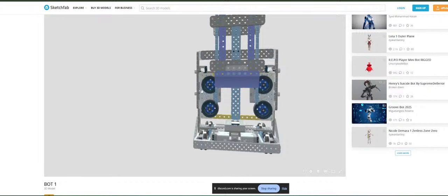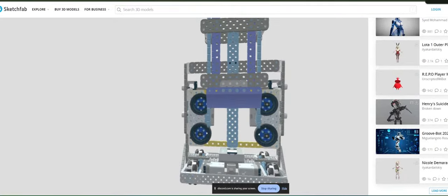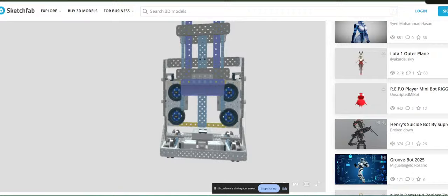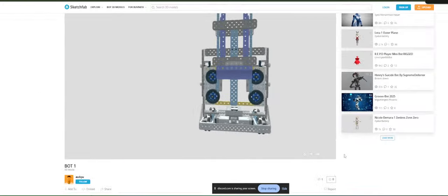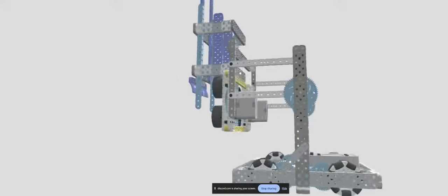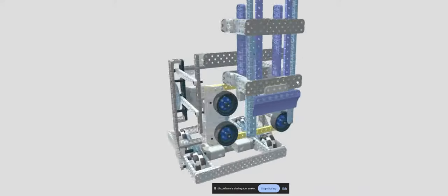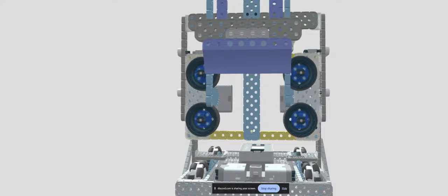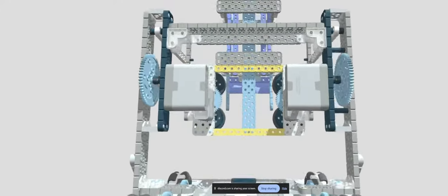The main issue with it is the spacing at the front. On the CAD, you're going to see those 160 wheels. They're not meant to be that. They're meant to be the balloon wheels, because otherwise, if you just use these, the pin would just fall out and it wouldn't work. So you need to change those to balloon wheels. And on the actual 4 bar, we're meant to change the beams. The top beam should be a 14, and the 2 bottom beams should both be 13s. Other than that, it should work. I agree.